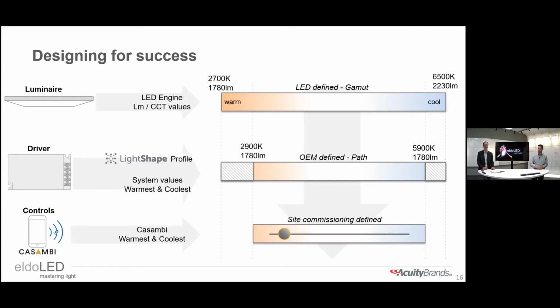Next to that, the application is ensuring that the brightness remains the same, even when the two different LED colors have a different brightness. Because 100% cold white gives you more lumens than 100% warm white. And an end user expects it to be equal. And that's what LightShape is taking care of. They take out all the complexity there by just programming it into the driver.